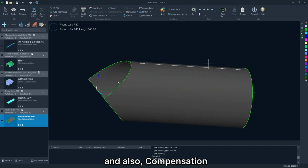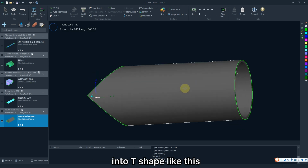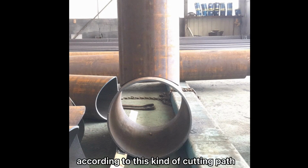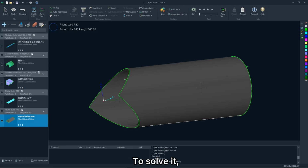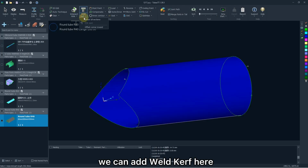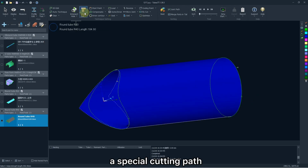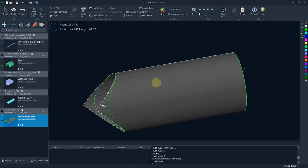And also compensation for special parts to be jointed into T-shape like this. If you just cut it according to this kind of cutting path, there will be the interference due to the differences between the inner and outer control. To solve it, we can add a weld curve here. Then TubesT will automatically generate a special cutting path to offset the interference.